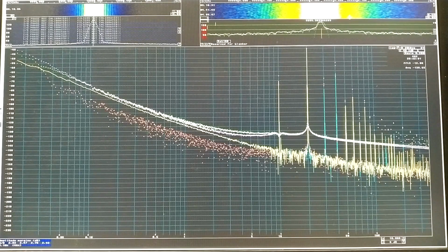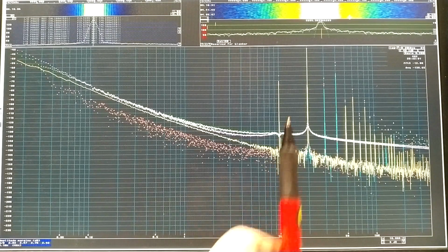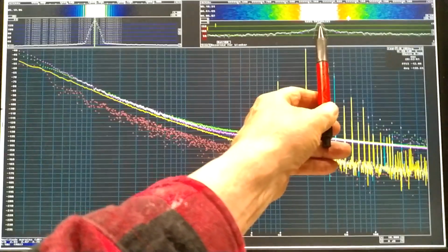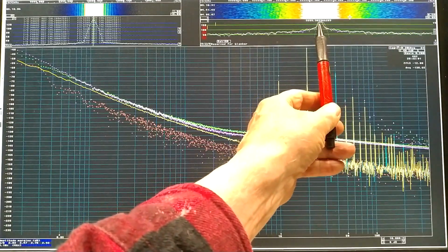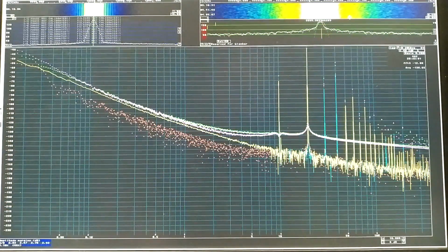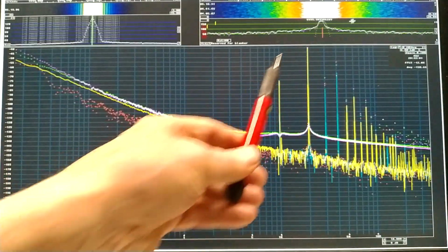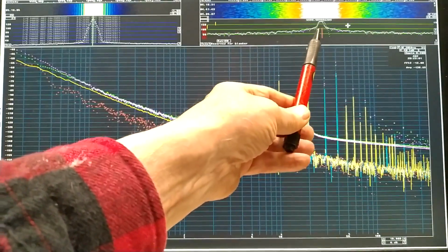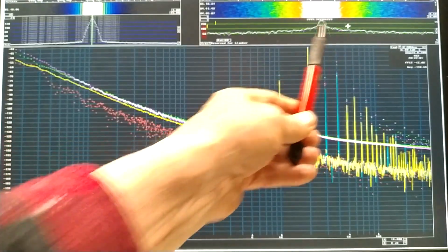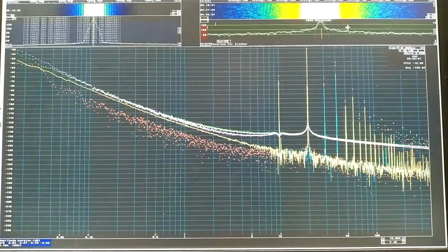Maybe it could be related to the fact that the carrier here is far from center on the filter. To be able to go down to very close to the carrier, I have set a filter shape that is not really what it should be. It should be more flat, so I could have the signal totally within.